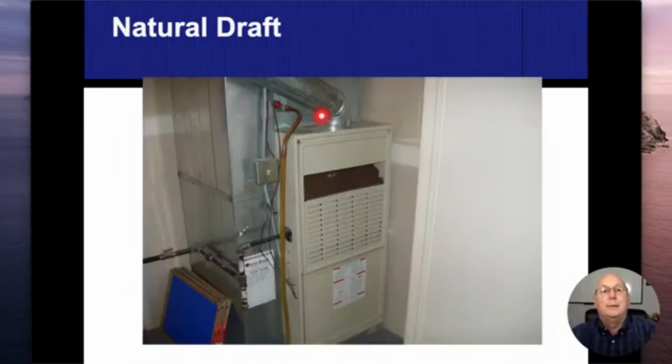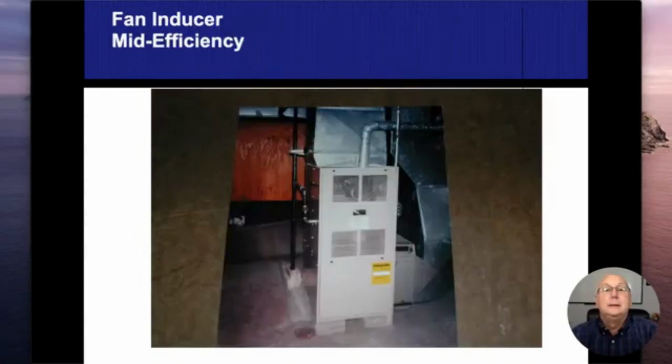This one here, I got a flexible drain. I do believe that's less than 6 inches away. And even if there is no burning, scorching, or anything on there, I'm going to go ahead and start calling that one out too. Another natural draft furnace.